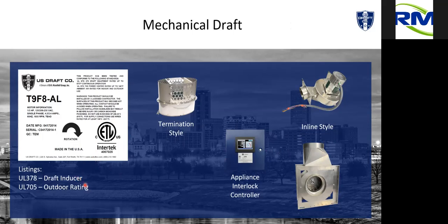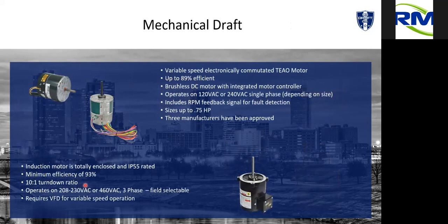and outdoor. All of our motors are standard off-the-shelf motors. We use EC motors, 3/4 horse and above. We're actually moving to 1 horse on the EC motors. Above that, we go to a 3-phase motor, which is an off-the-shelf Marathon motor. We try to make it as easy to service as possible if and when a motor ever does fail.